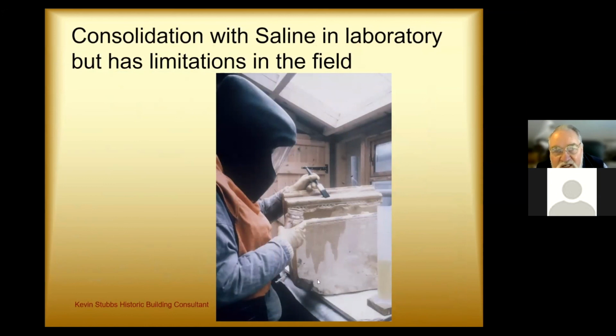The alternative was consolidating with silanes. It works beautifully in the laboratory where your stone's absolutely dry. It's highly carcinogenic, so you have to be careful how you put this material on. It's supposed to coat only the internal surfaces of the pores, leaving them open for the stonework to breathe.